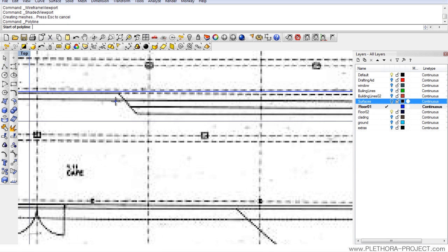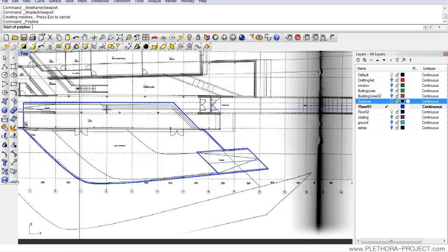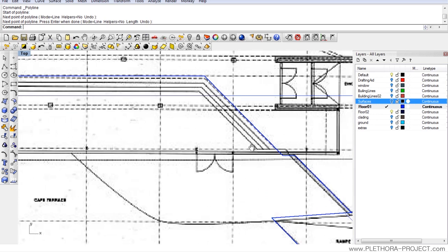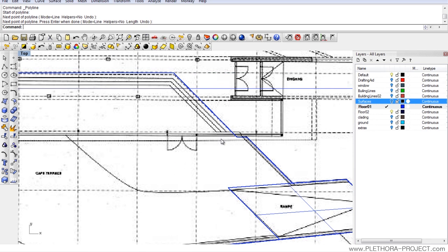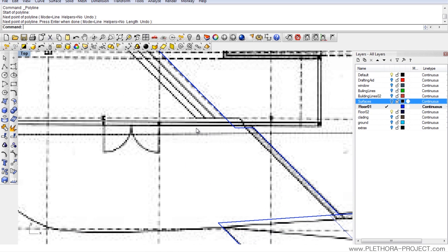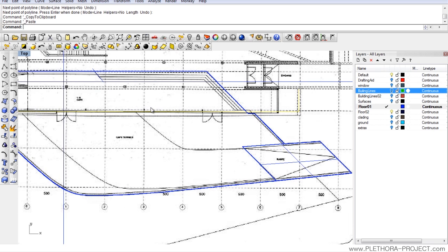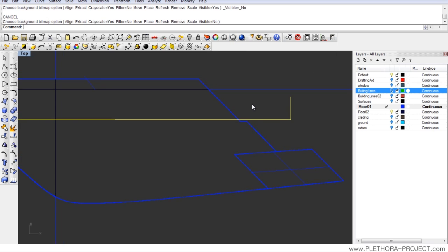The first thing I want to do is just, right, what we're gonna do is just draw these profiles and draw these lines of boundary. So in this case, it should get till the end of the volume, right? So in this case, it should be this line, right? So we're gonna make a copy of that line by pressing Ctrl C and Ctrl V and switching it to our layer. So now we see that we have a blue line, so that would be the boundary of that stair, right?